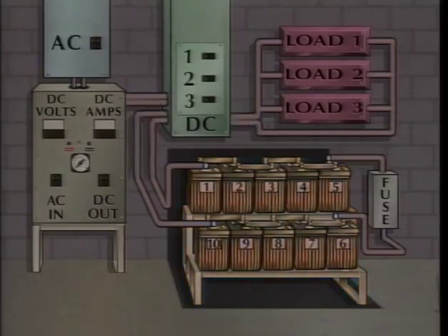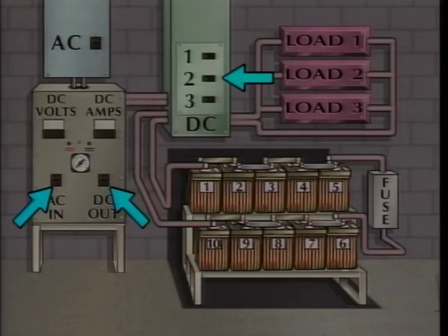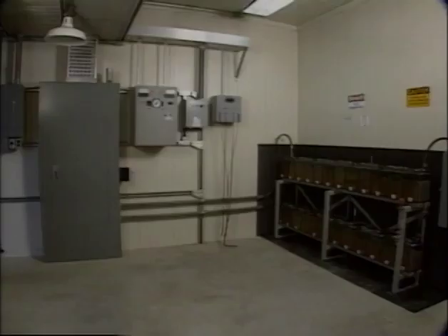The components of your DC control system may vary some from the ones illustrated here, but the principles of control that they represent are the same. The breakers in a DC control system are operated in a specific sequence when a battery charger or a battery is replaced. Because DC control systems can vary some from the example used in this program, it's important for you to become familiar with your company's DC systems and how they work.